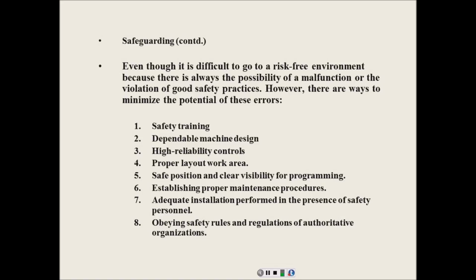You'll put that robot on what we call high-speed teach. So you've got two T's on that pendant. So when you go to your mode select, our robot has a mode selector on the teach pendant.